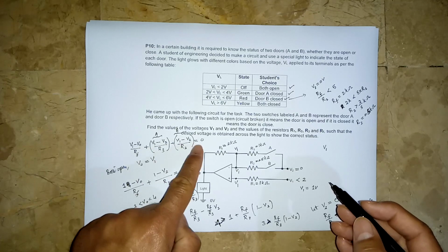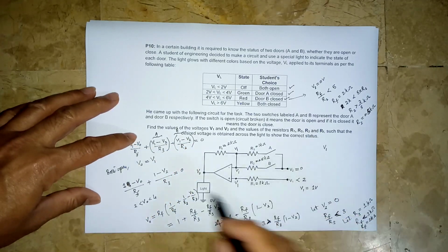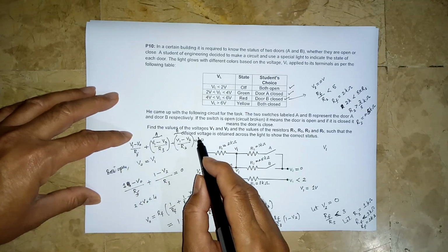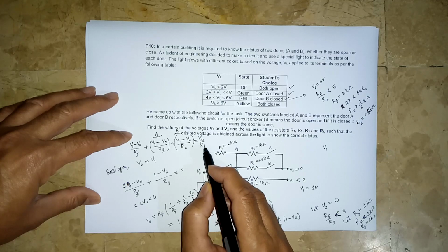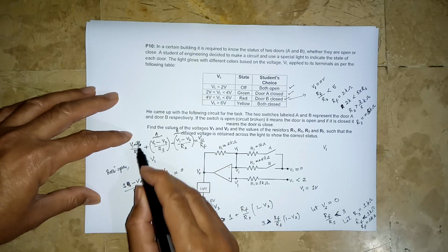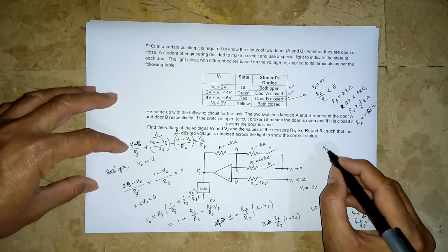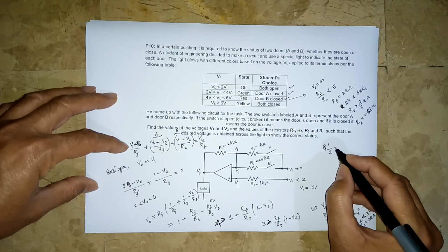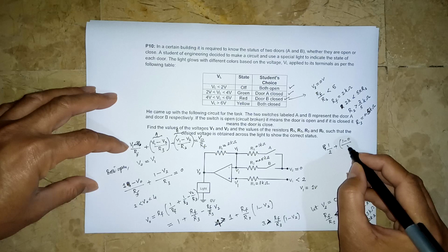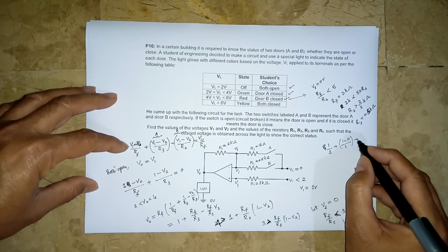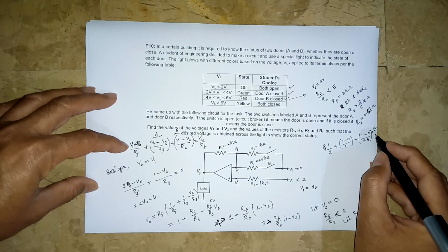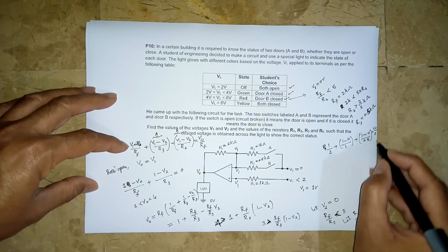Let us see whether this gets satisfied or not, and whether VO is satisfied in this equation. So in this equation, we can see if VO over RF goes to this side, we can eliminate it on this side. So let us see if we can satisfy this. V1 is 1 over RF, which is 2 kilo ohm, plus 1 minus 0 over R3, which is 1 kilo ohm, plus 1 minus V2, which is 0 over 0.5, is equal to VO over RF, and RF is 2 kilo ohm.